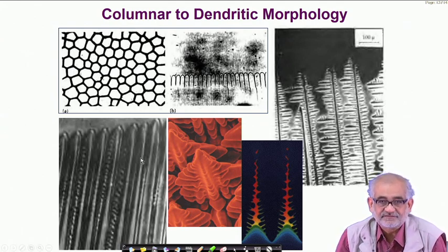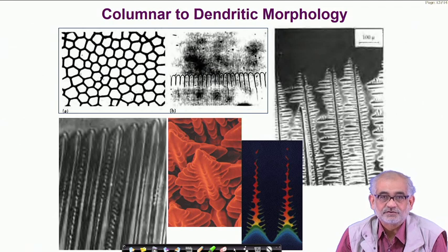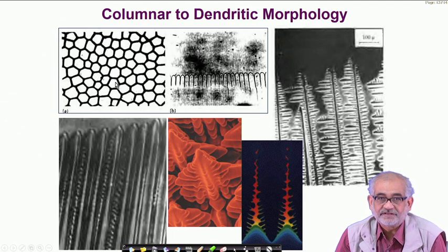So we first get very ultrafine structures, followed by gradually coarser structure, and finally in the middle we are likely to see equiaxed zones where the rate of growth of the crystallite in all three directions is about the same. But in between, from the core where we have equiaxed zones to the surfaces where we have chilled or ultrafine zones, we are likely to see directional solidification.